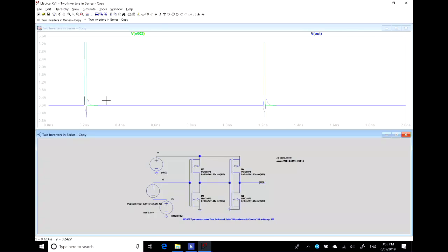So this is an inverter, it's a logic gate, an actual one. Logic gates swallow short pulses. If I were to model this using a transport delay, that short pulse would appear at the output. But it doesn't. We get nothing at the output.